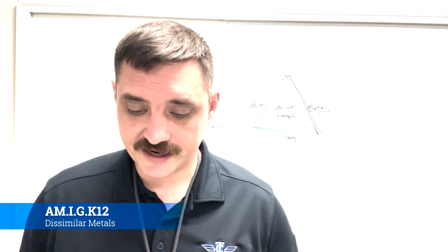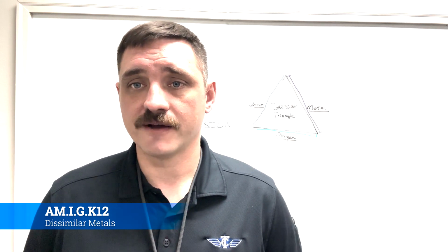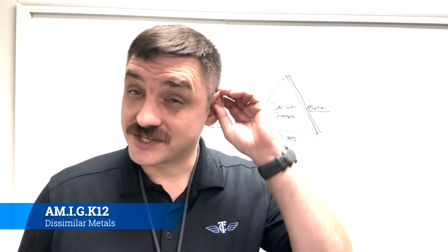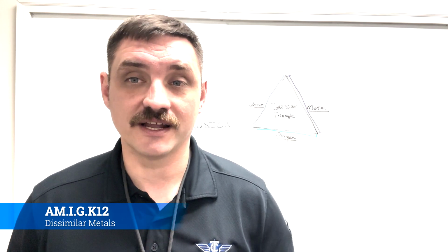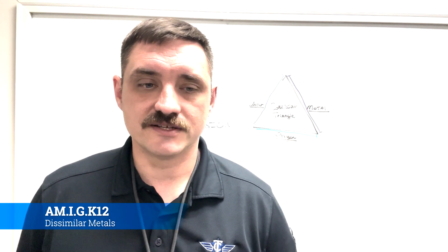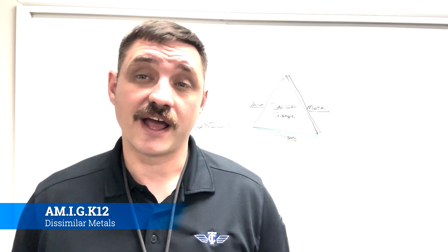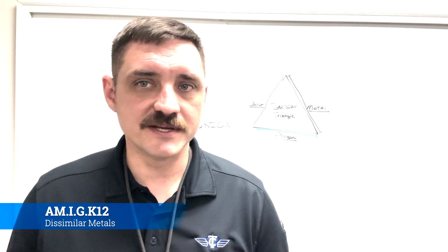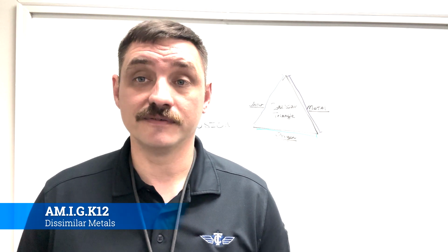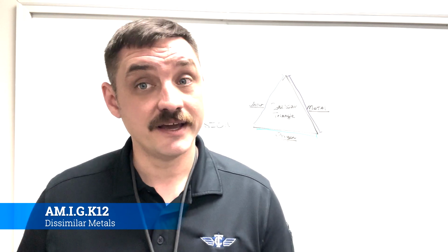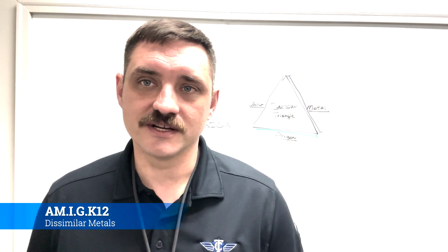But essentially, in order to protect against dissimilar metal corrosion, which there's a lot of on aircraft, you always want to have things separated. As a general rule, you want to keep things from touching one another. Things don't really get along, and metal to metal contact is generally bad. So you're going to have some sort of separation in there, be it a grommet, an Adel clamp, or some sort of standoff, or maybe even taking a bunch of high temp RTV and RTVing the whole thing up, and then setting the line or metal or whatever it is you're trying to separate in there.